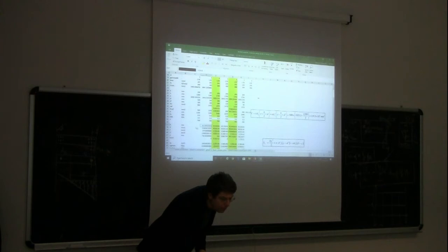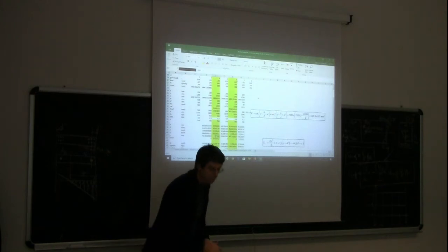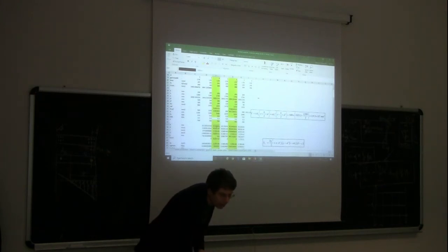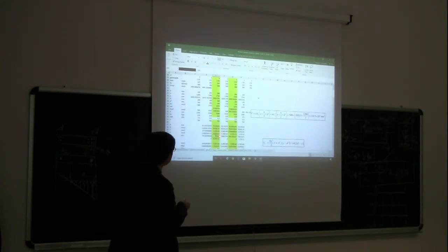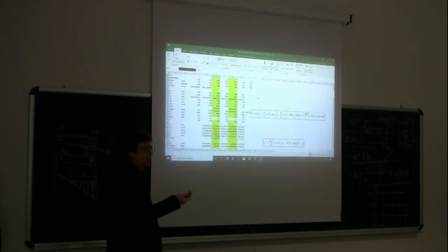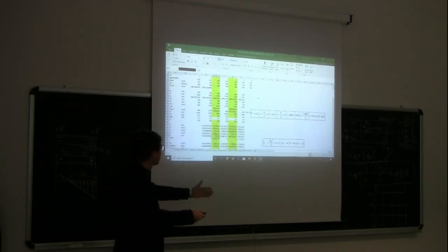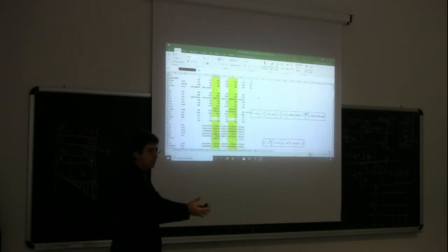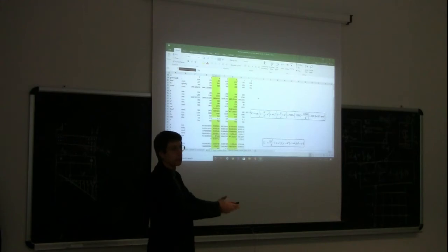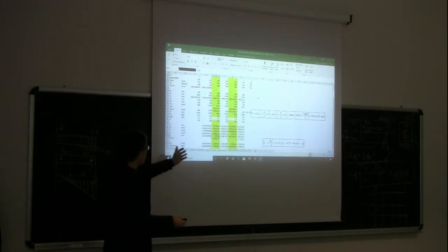So while A, B, C, and D are formulas, as you can see inside here, there are different formulas. Y is a number. So what you can do, you can set up an initial value of Y, 400, for example. We don't know how much it will be. Of course, if you're expecting something between 0 and 1000, in our case, you don't put 1 million inside that. You put 100, something that may be reasonable, because otherwise the program may not converge to the right solution. So you put 100, and then you go on the function here.